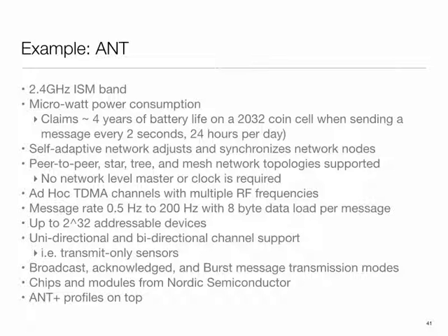The basic thing here is they were aiming for years of lifetime on a coin cell and still have a rich enough networking capability. So what these guys did is they operate on a purely synchronous basis. They have time division multiple access, so everything is time slotted. Everyone knows when to transmit. And then very tiny packets, just 8 byte packets, going out. Okay, so very tiny payloads. But within that, they optimized the hell out of it.